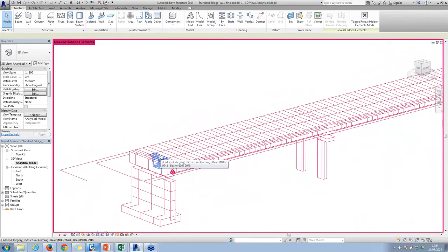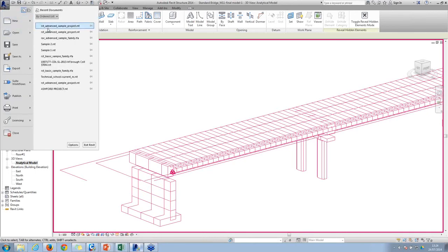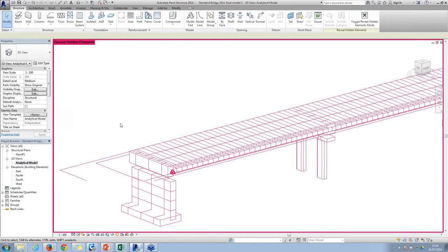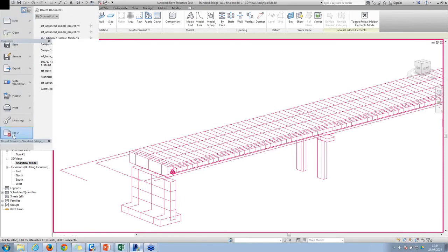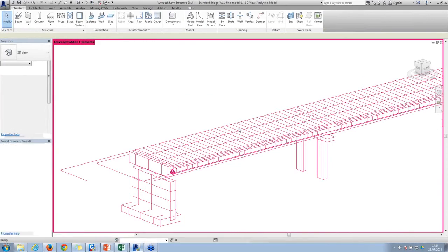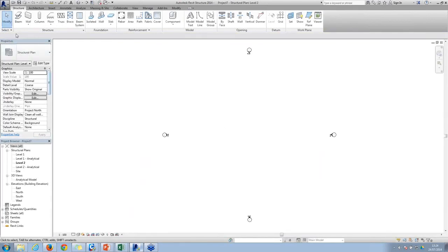It can be a plate model, it can be a grillage model, any type of model you can bring directly into Revit through IFC file format. And the other way around, if you have an existing Revit model, then you can bring the Revit structure model into Midas Civil. So for this, I'll just take a general structure as an example. Okay, so I'll just close this.